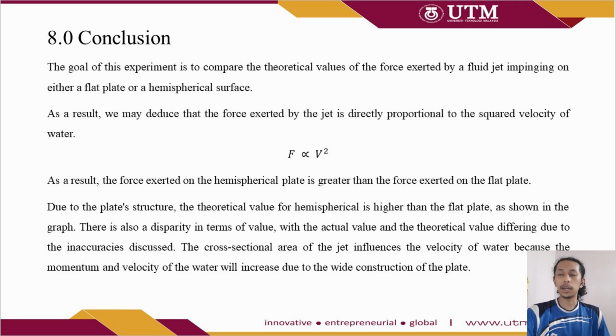For the conclusion, the goal of this experiment is to compare the theoretical values of the force exerted by a fluid jet impinging on either a flat plate or a hemispherical surface. As a result, we can deduce that the force exerted by the jet is directly proportional to the square of the velocity of the water. The force exerted on the hemispherical plate is greater than the force exerted on the flat plate.